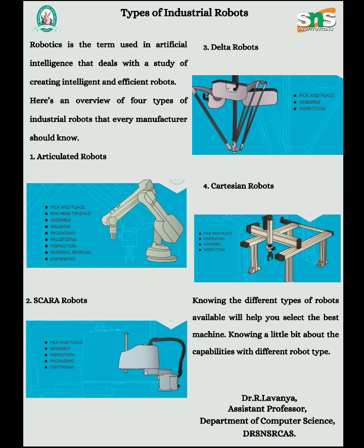That said, the custom nature of Cartesian robots can make design, specification, and programming challenging or out of reach for smaller manufacturers intent on the DIY approach to robotic implementation. They are unable to reach into or around obstacles easily, and their exposed sliding mechanisms make them less suited for dirty or dusty environments. With this, I'm concluding.